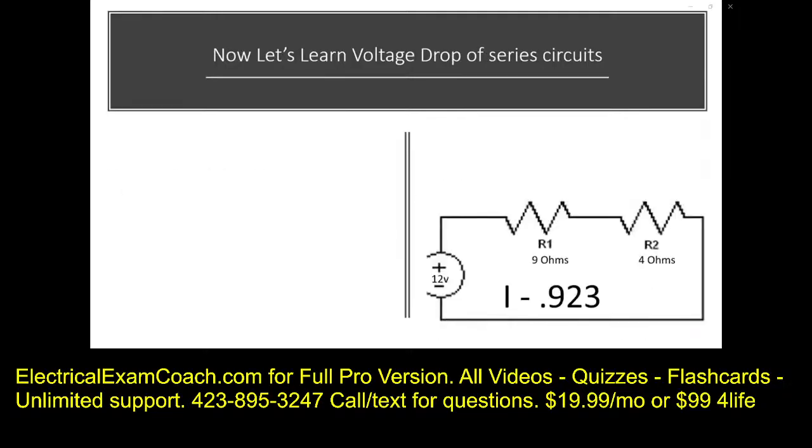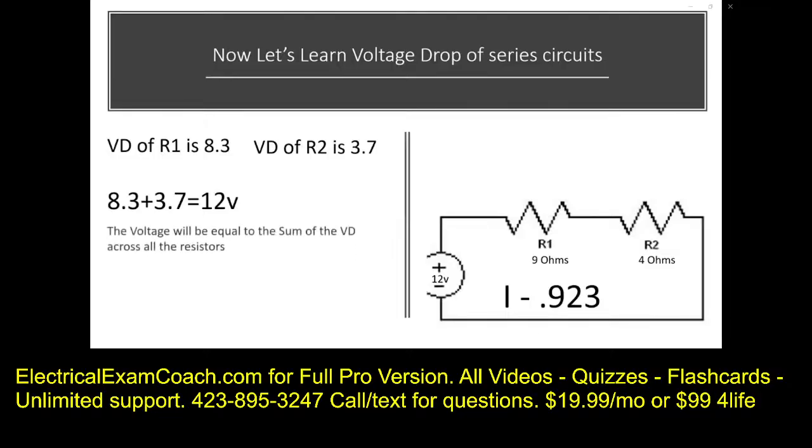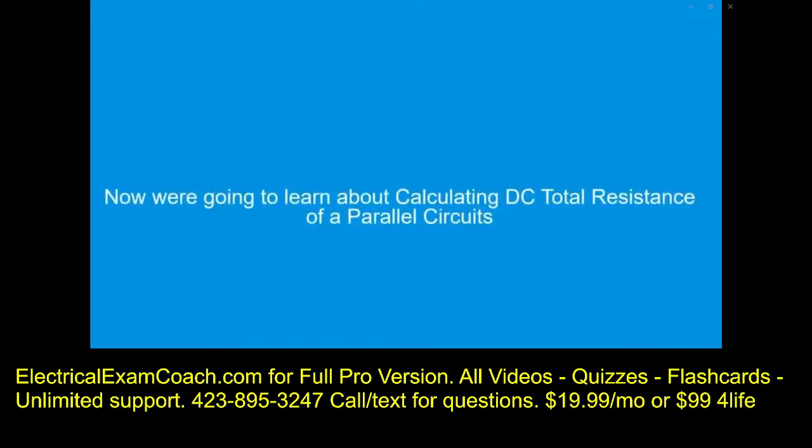So the voltage drop of R1 is 8.3 when we did our multiplication, and the voltage drop of R2 is 3.7. Okay, a quick recap. The voltage drop of R1 is 8.3. The voltage drop of R2 is 3.7. 8.3 plus 3.7 is going to equal 12 volts. The voltage will be equal to the sum of the voltage drop across all resistors, and that's how you double check your work. Now we're going to learn about calculating DC total resistance of parallel circuits.